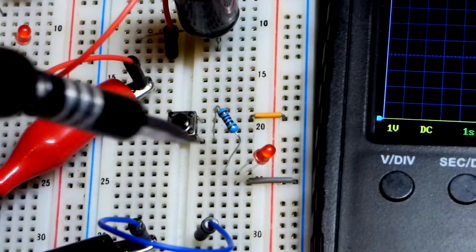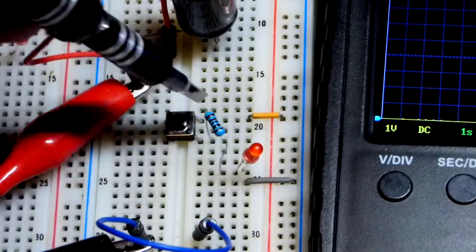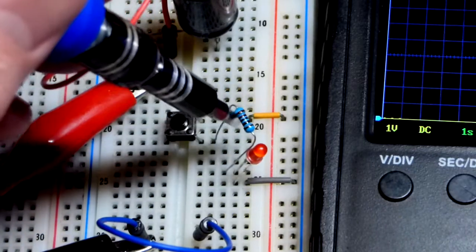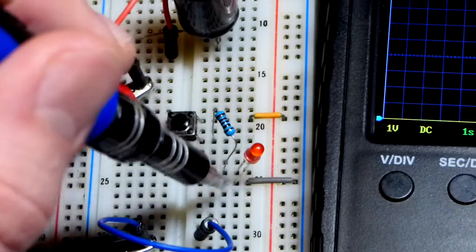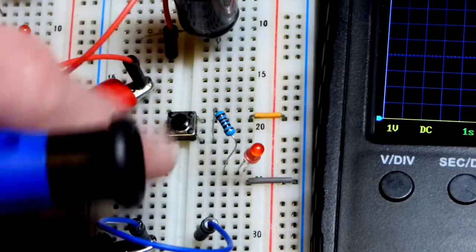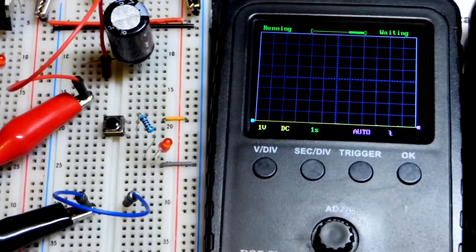And so here we are at the breadboard. I still have the LED, we'll remove it shortly, but we have that orange jumper from the positive supply to the top of the switch, bottom of the switch to a 1 kilo ohm resistor that's protecting the LED, in series with it, long lead the anode, short lead the cathode right there, so that it will light up when we press the button. Now you're also going to see the oscilloscope here.